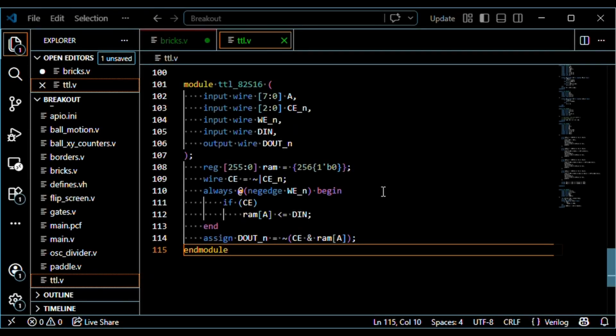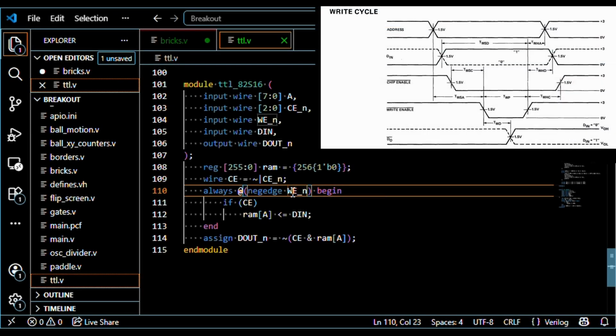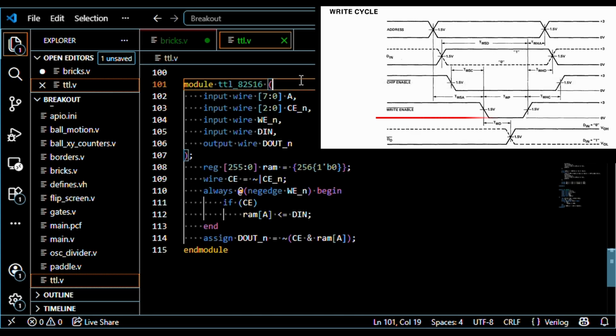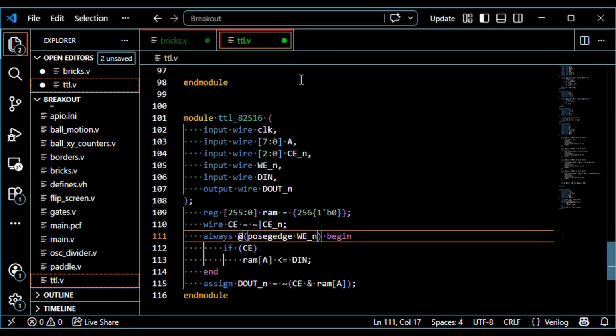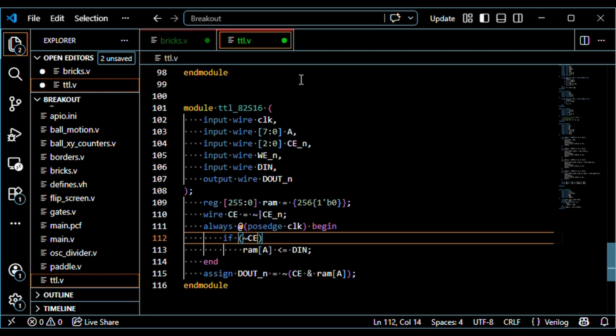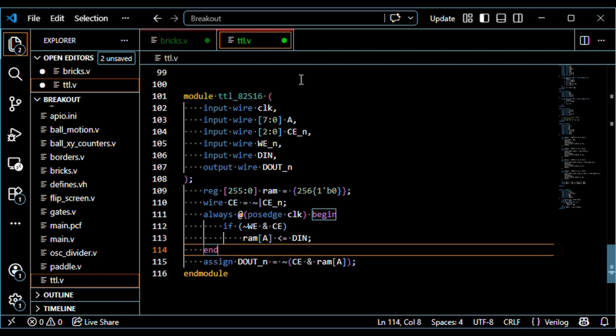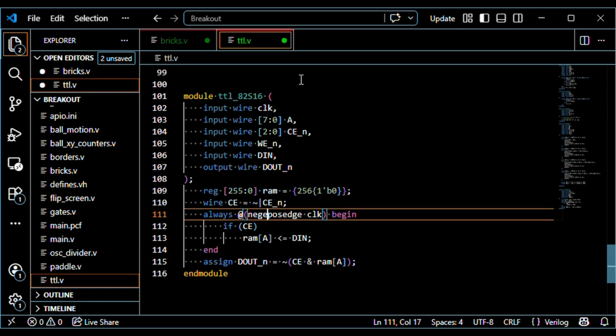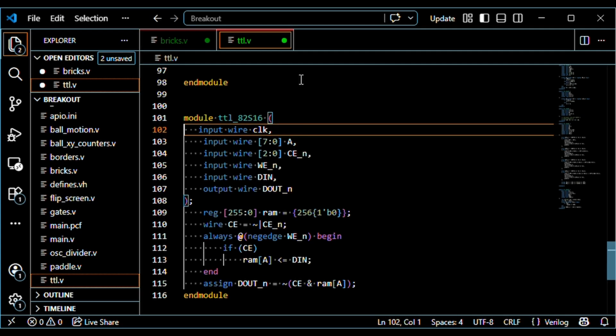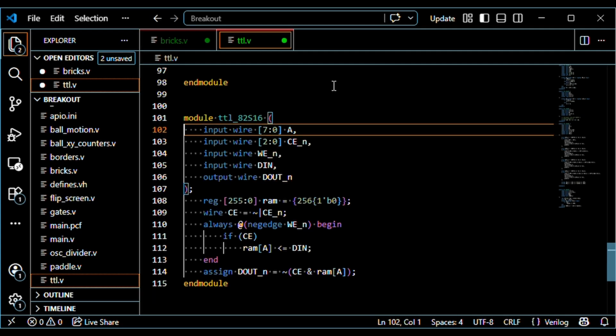So our nice SRAM module won't work for fill operations because we're not pulsing right. To fix this, we could introduce some clock for the always block, then check if WE is low and write the data in value to the selected address. My preferred method is to simply fix the WE line to properly pulse for every write during fill operations.